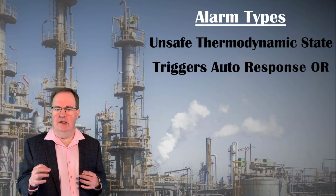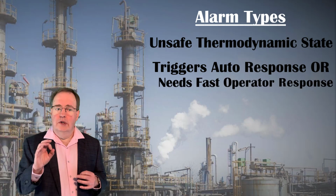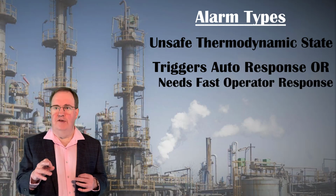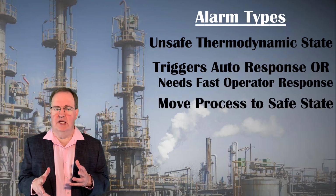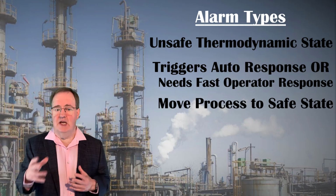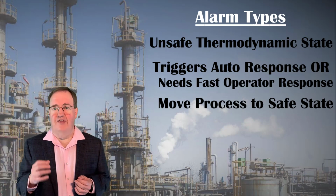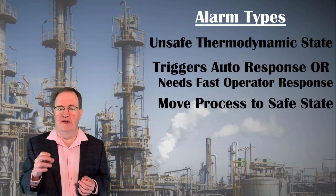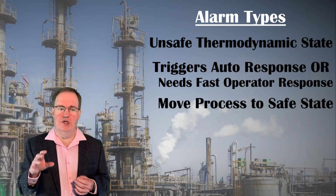An unsafe state either triggers an automatic response, ideally, or triggers an alarm which signals the need for an operator response. The operator needs to quickly assess the situation, make sure the process is moving to a safe state, often by shutting down or pausing feed, and then assessing whether the unsafe state is real or fictitious, and whether a restart should be attempted.